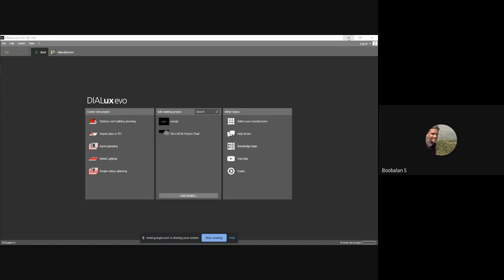So now after fixing the lamp and then going to measure, here I am just placing graphically and checking, arranging, maybe lux commands, and I am going to rearrange the lamp positions and verify here. Once I get the simulation result perfect, I am going to go with that manual method, right? So if we fix it manually, experts say that working hours will reduce and I will get efficient output. So these are the different advantages of using these softwares.